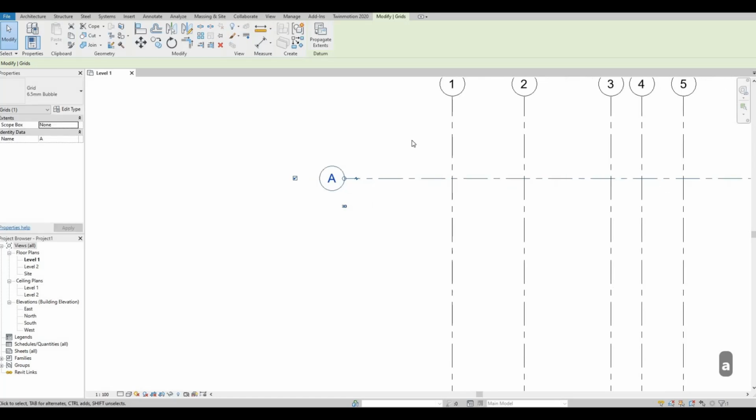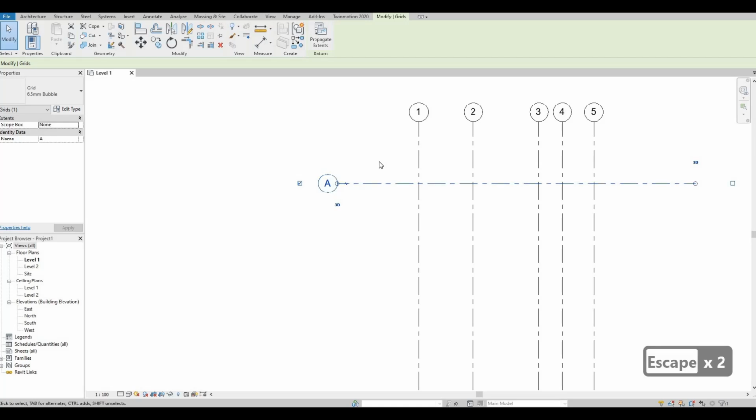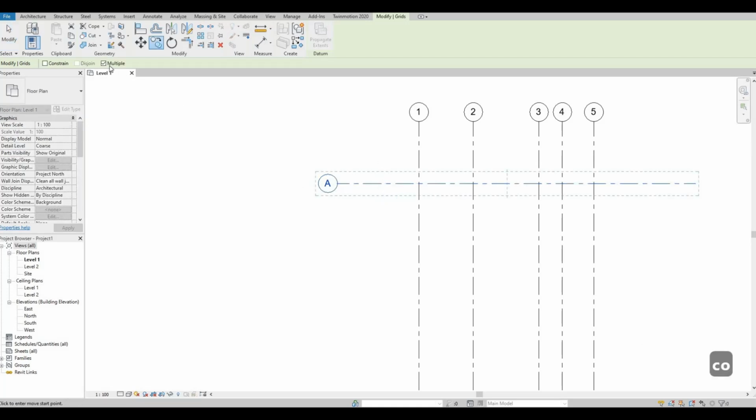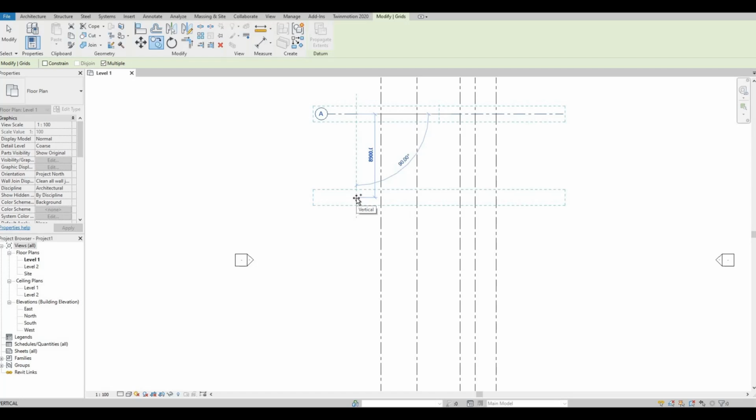Click on the space, and now this is still highlighted. So if we click it again, CO, that's copy. Multiple is already checked because it recognized that's the last thing that we did here. And then here, what we're going to do is pull it downwards so that it knows that it will go down. And if you notice, it will change to B and so on and so forth. So the sequence will be correct. Revit will recognize that as well. So 1830.